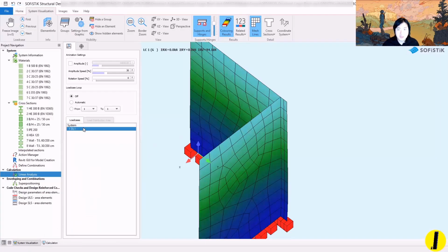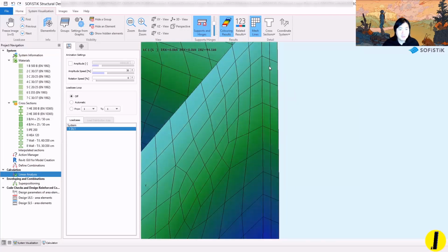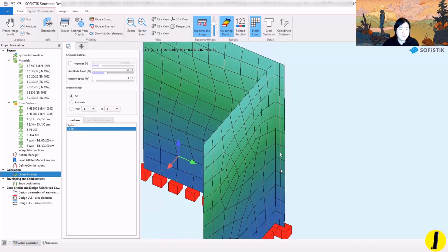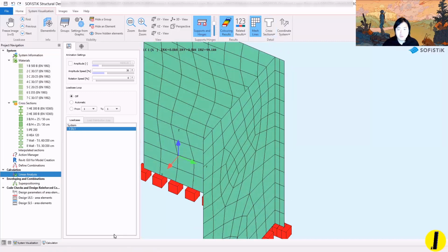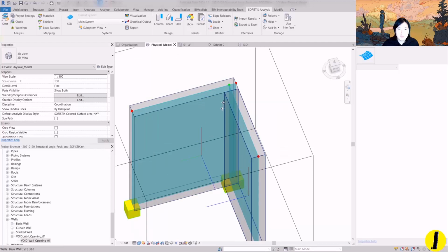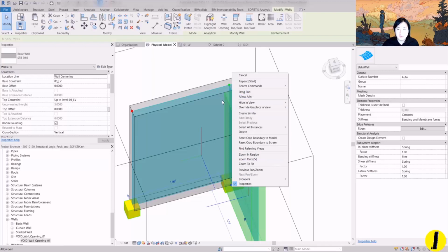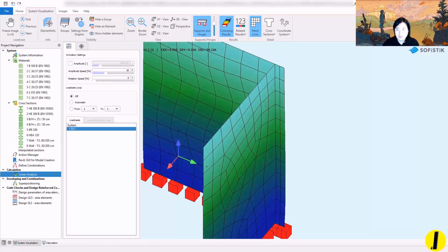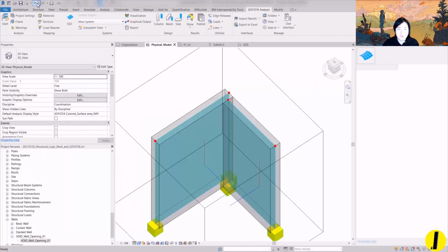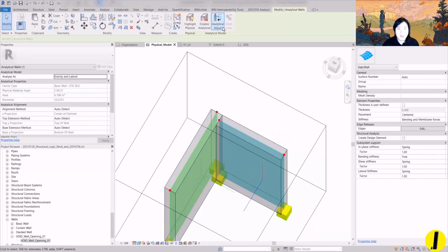If you see now the dead load result, they are actually behaving together, not individually. But because of the join, the extra piece here is not something that we want to have in Revit. So I guess this solution is not good if you model a wall and dissolve the join at the end of the wall. This result is not very good for the calculation in Revit. Let me undo this join. I'll leave it as it is, and perhaps I have another idea.